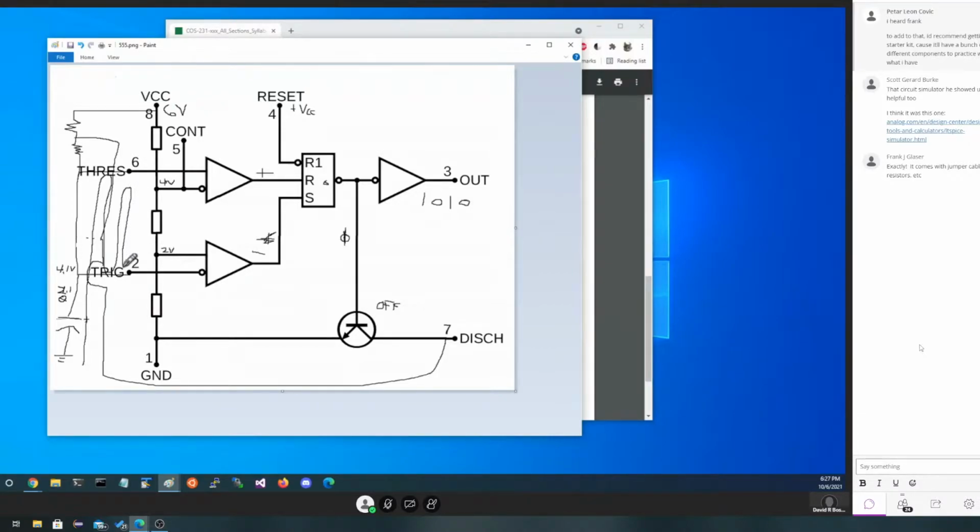There's not nice sine waves like this. It's going to actually follow an exponential curve. But because of that, with the very first period, the first high signal is a little bit too long. So we design our circuits so we don't care about that. But all the rest will remain with the capacitor having a value between 2 and 4 volts.